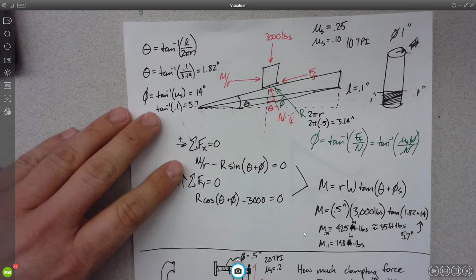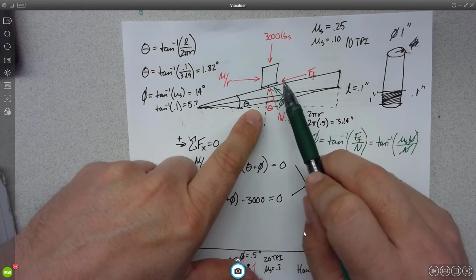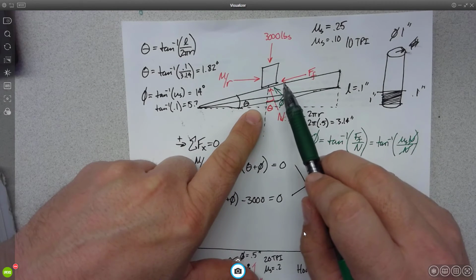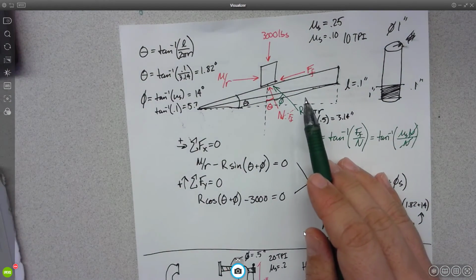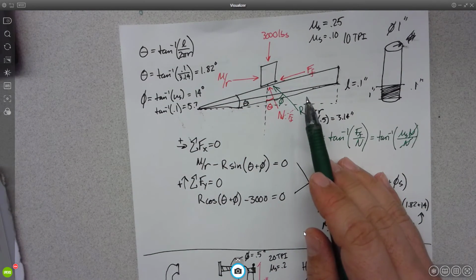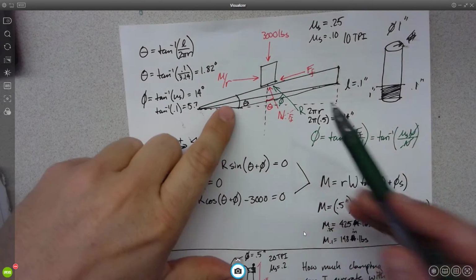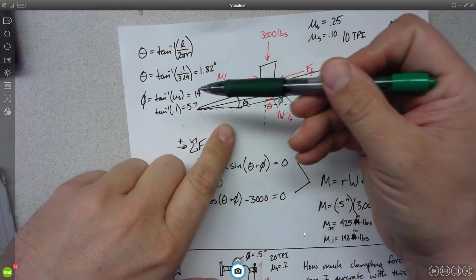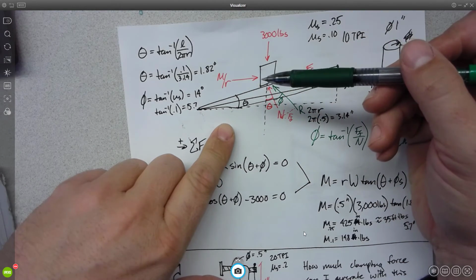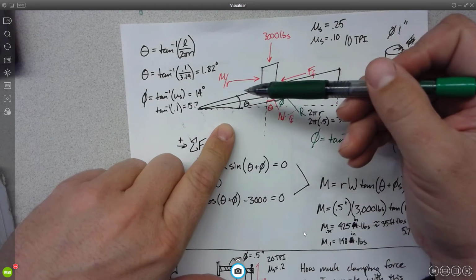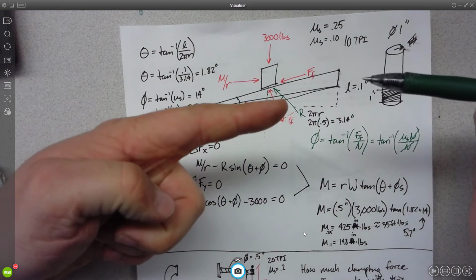Maybe you're reducing the amount of friction. Think about which way I'm pushing the block. Am I pushing it up the hill or down the hill now? Right? So when we're tightening, we're shoving this up the hill. We're pushing that up the ramp. Okay? When we're loosening, we're pushing it down the ramp, which should inherently be easier. Right? So pushing it down the ramp is going to be easier than pushing it up the ramp.